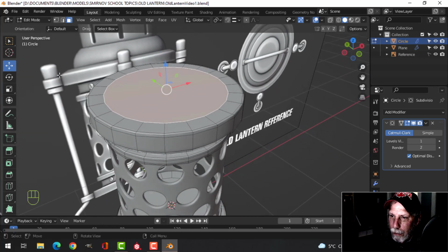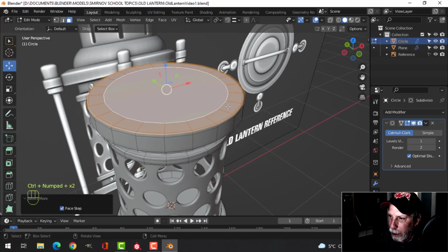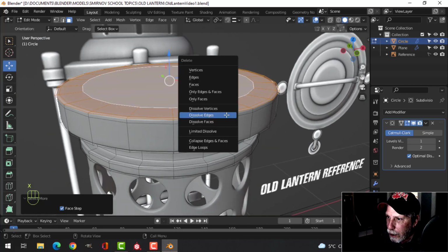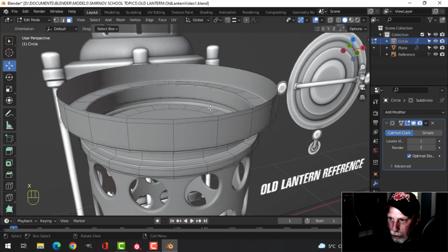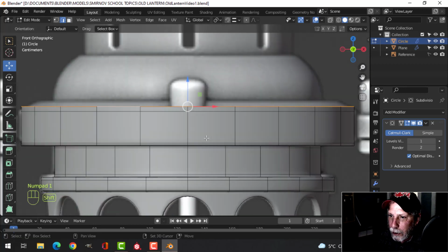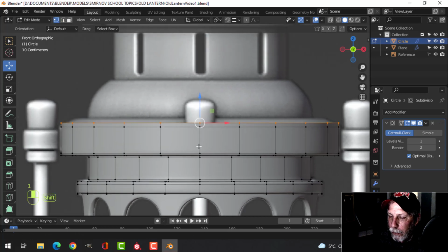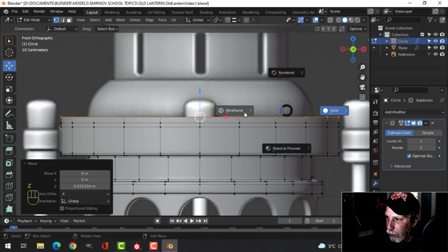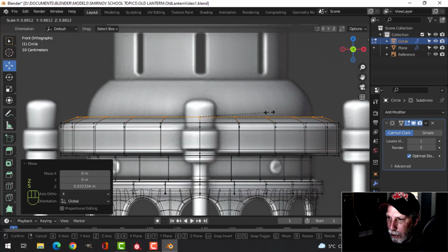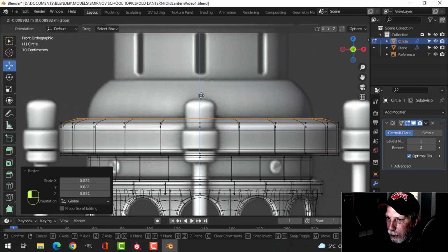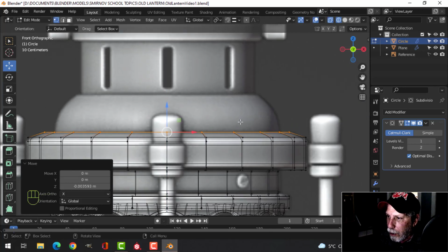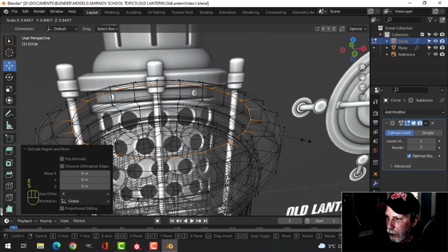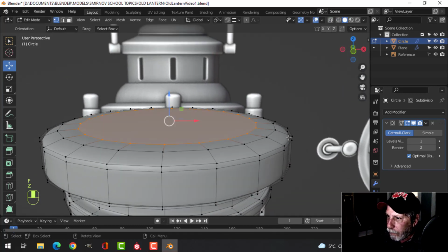Let's see what it does. Okay, it comes up and then it angles. So let's Control plus a couple of times to there, maybe just to the outer edge, and let's delete those faces. I can leave that edge there for now. And grab this. Let's look from the front again. And how about we press 1 for vertex selection, E to extrude, and click. Come up. We can go with a wireframe if we want it. S to scale. We'll do it like that. But this is going to be a separate piece, so let's just close this up and go E and S, F.